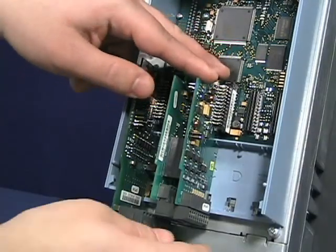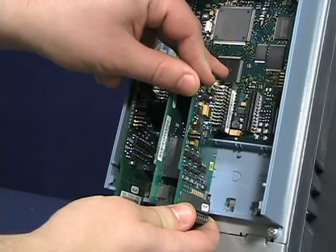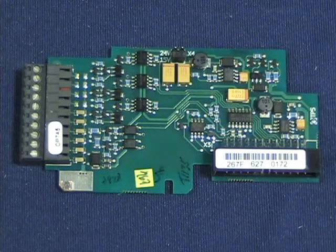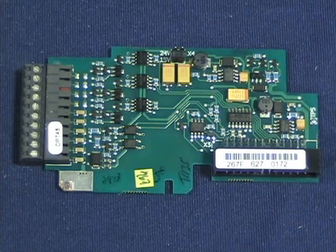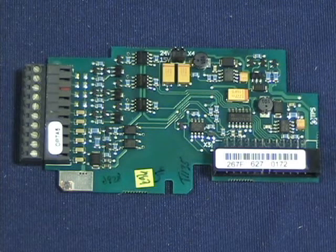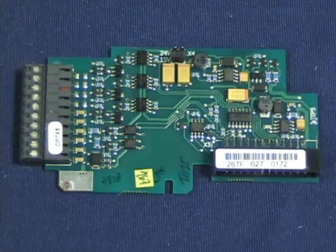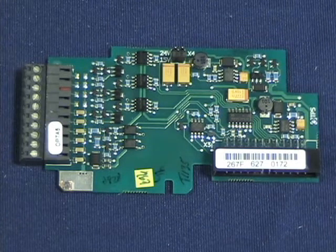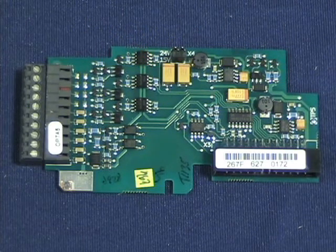If the section requires encoder feedback, slot C will contain the encoder feedback card. This encoder card, shown in the video, is the OPT-A5 card. This card has input terminals for the phases of your encoder: phase A, phase B, and phase Z if applicable. This specific card also gives the option on how much voltage the drive should output to the encoder. A jumper on the board lets you choose whether the drive sends 24 volts to the tach or 15 volts.